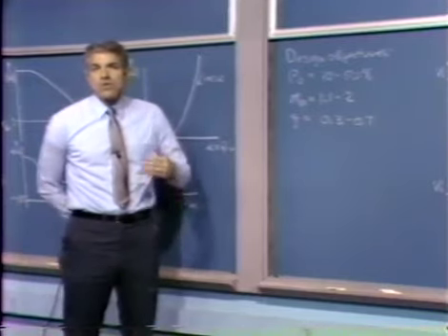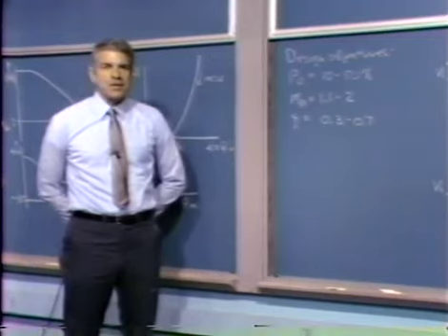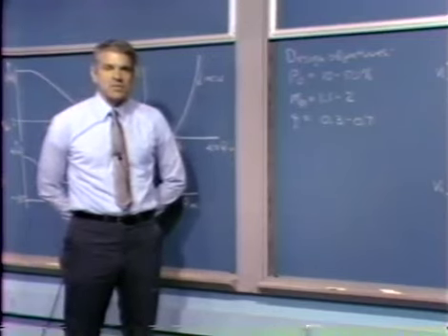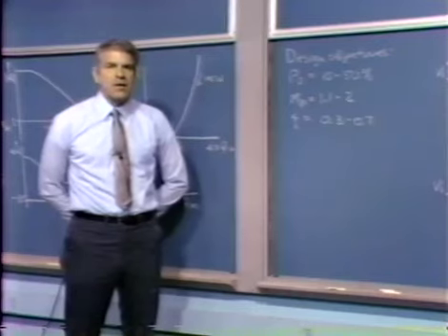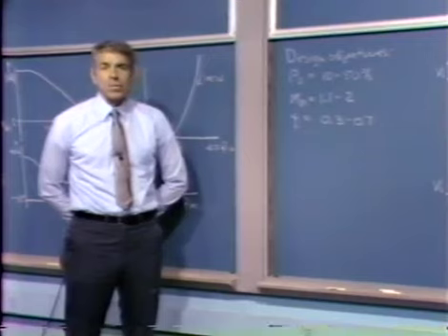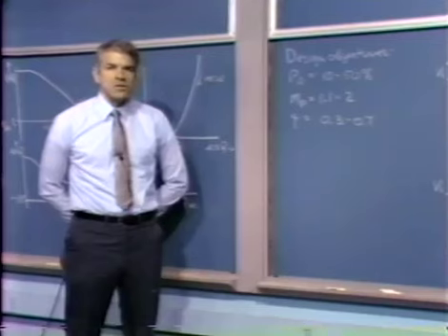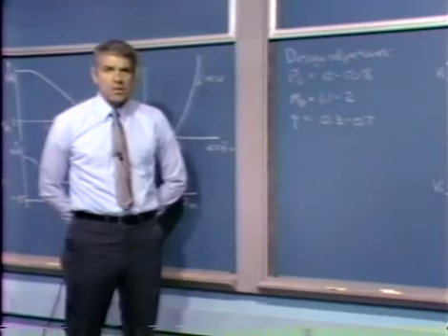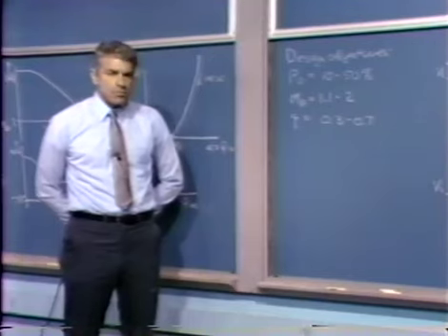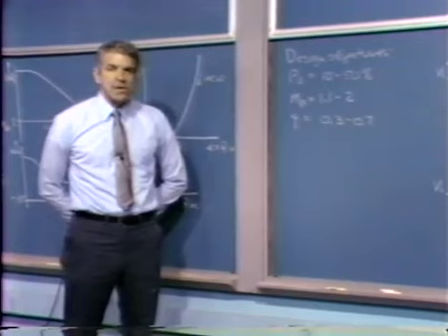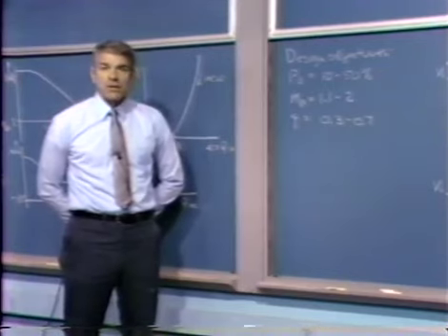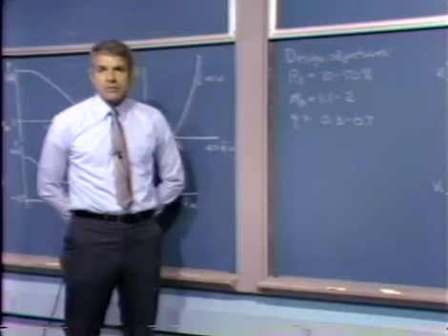Furthermore, the degree to which we're willing to approach instability, if you will, the proximity we're willing to come to a system that's unstable, depends in part on how sure we are of the parameters. Will they remain fixed, or will a system that has a minor stability problem today get worse as time goes on because of some unfortunate change in parameters? So we really have to have a good feeling for the actual details of the system when we go through this process. But as general guidelines, we find, of course, that as we compromise stability, as we go to a relatively less stable system, the advantages we gain in exchange for that are generally a higher crossover frequency.